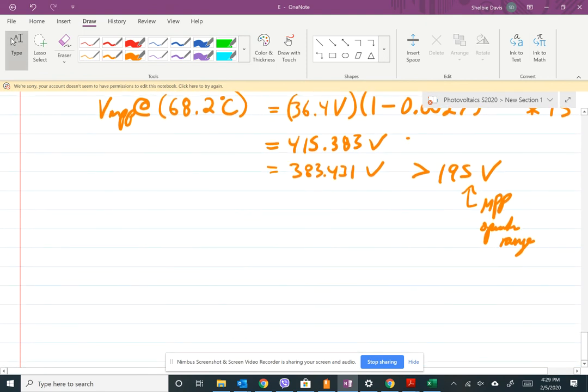Now, the other thing is we need to check to see if there's going to be any clipping. Clipping means that you reach an AC output, not DC input, but AC output that is above the specification. It will begin to clip the power, meaning it will not output that much power. It will just waste the power. That has to do with the fact that it's a protection against the electronics getting too hot. Okay, and the whole starting on fire situation, which was brought up last time.